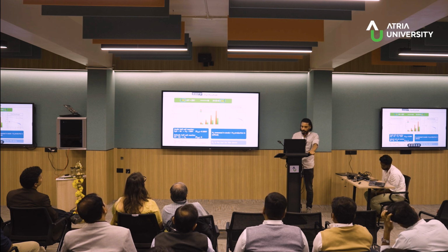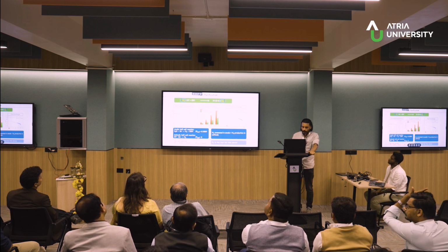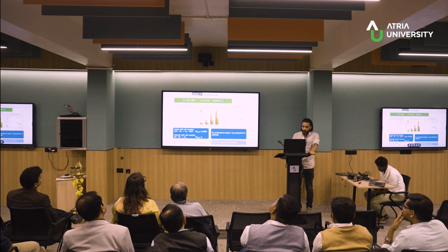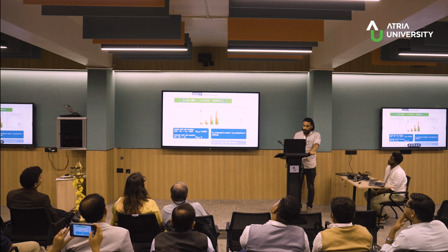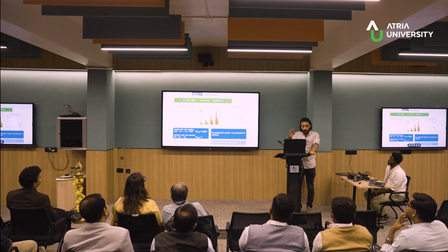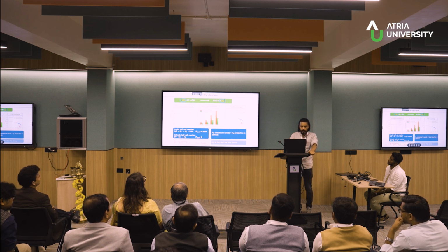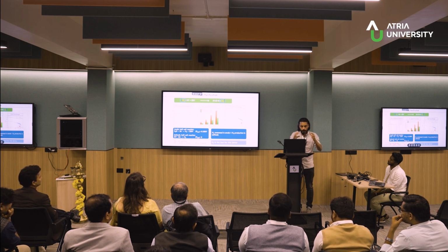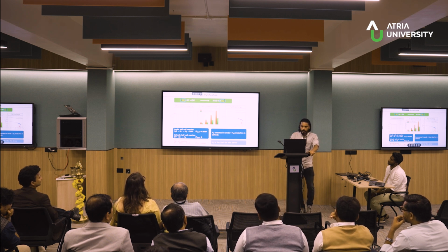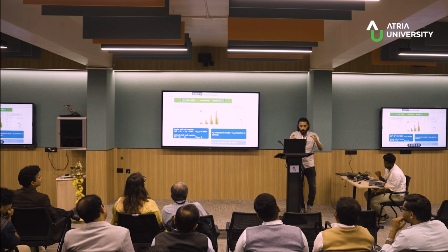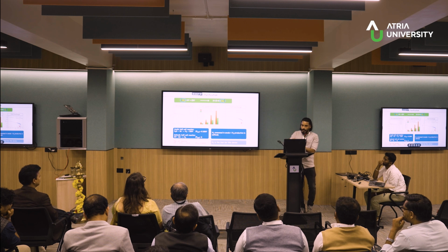That is what is shown in this particular plot. When there is no hydrogen, as shown by the red trace, the cell voltage abruptly drops to 0. And when there is hydrogen, the device can be run for several hours, which means hydrogen is the electroactive species. But the most important thing is there is no net consumption of hydrogen. If 10 molecules of hydrogen are consumed, there have to be 10 molecules of hydrogen evolved in the cathodic half cell. There has to be a one-to-one correspondence between hydrogen consumption and evolution. And this understanding offers opportunities for fuel purification.